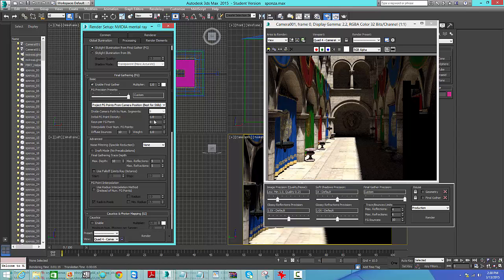The default that it comes in with is 250. The whole point is, say a point comes out here, it's going to shoot the rays out until it hits a surface and bounces. And the bounces are determined by how many bounces you have set in the scene. This is set to 10 for this scene, but it comes in defaulted at 0.